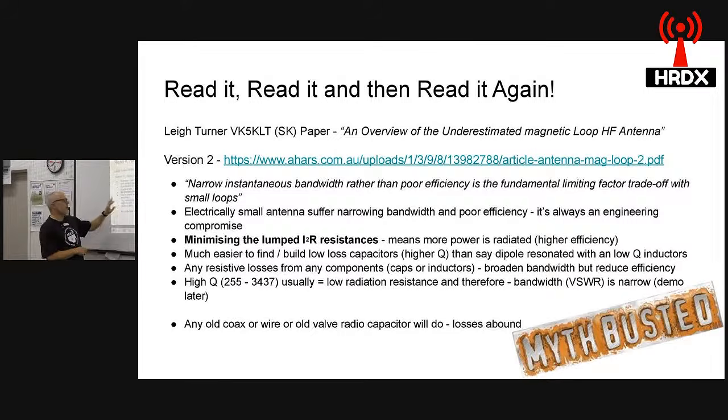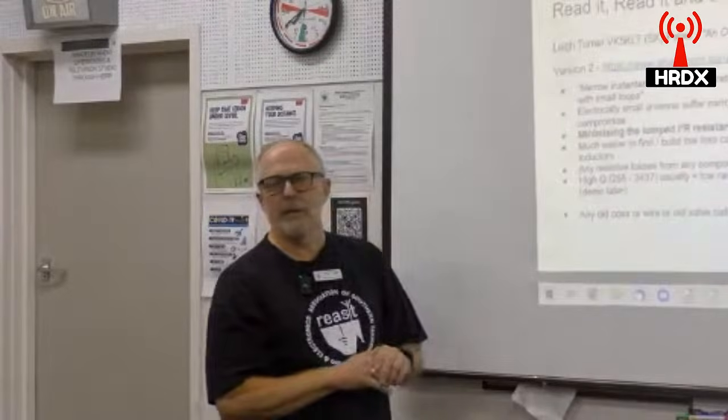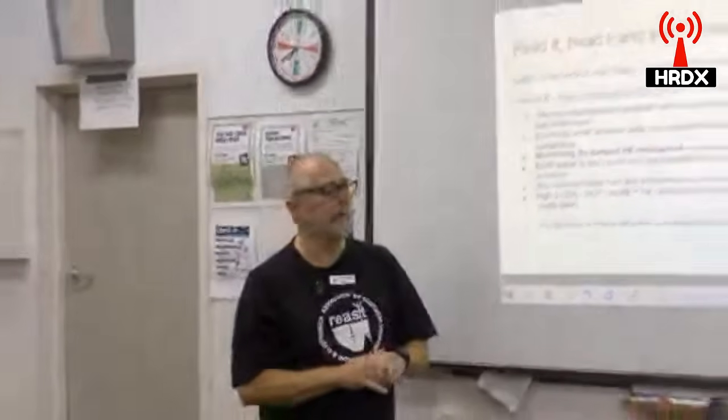Okay, reduction of any of those ohmic resistances, whether it's your connection to the vacuum capacitor, the loop itself, or the connection between them, and I'll show you how I've reduced this down. And in fact, thank you to Alan for lending me a 4-wire resistive meter, enabling me to actually demonstrate how low you can get if you try.